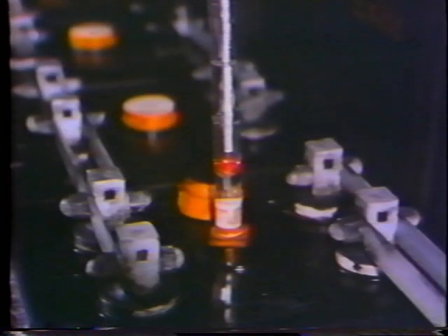The electrolyte in this cell contains acid, so the internal parts of the cell are sealed in a container that is acid resistant. There's a filler plug at the top of the container. You can remove the filler plug if you want to take a sample of the electrolyte to test its composition, if you want to check the temperature of the electrolyte, or if you need to add water to the cell. Most filler plugs, like this one, have a vent hole to allow gases formed during chemical action to escape from the cell. Okay, that's what a typical secondary cell looks like. Now, let's see how it works.